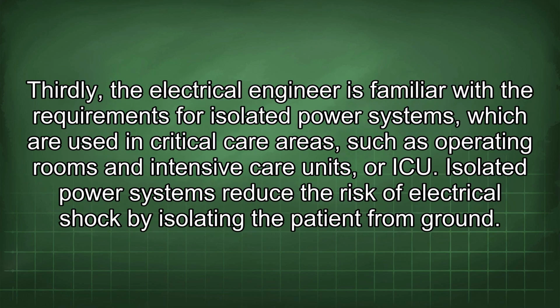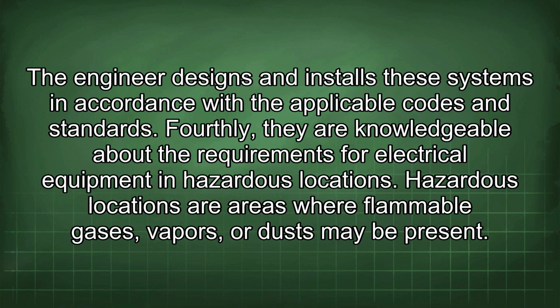Thirdly, the electrical engineer is familiar with the requirements for isolated power systems, which are used in critical care areas, such as operating rooms and intensive care units, or ICU. Isolated power systems reduce the risk of electrical shock by isolating the patient from ground. The engineer designs and installs these systems in accordance with the applicable codes and standards.